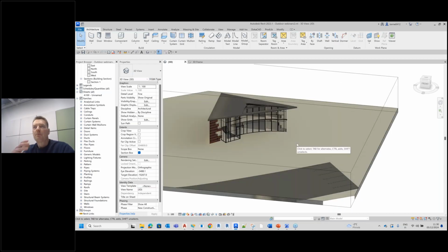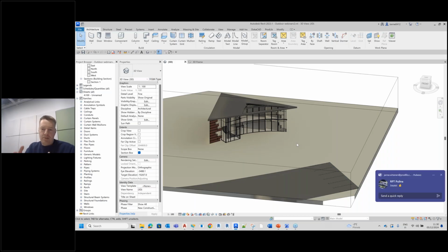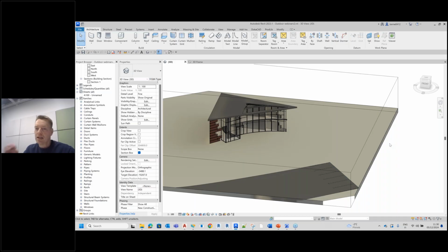One of the challenges with Revit, for example, is that if you are downloading lots of your own content and libraries, and you save them to a template of your company, it can get massive. So what we can do is access all the content in the ProdLib library, browse it, and just add it case by case to each project. So it doesn't need to be preloaded to any project template.